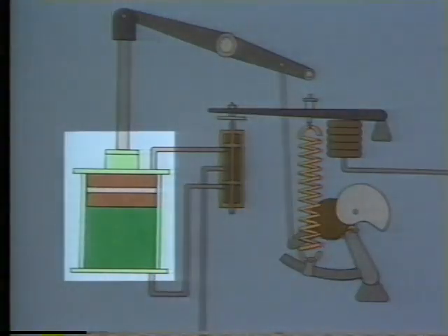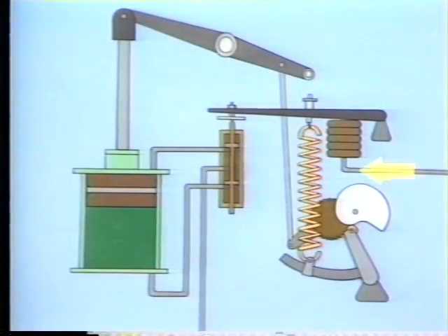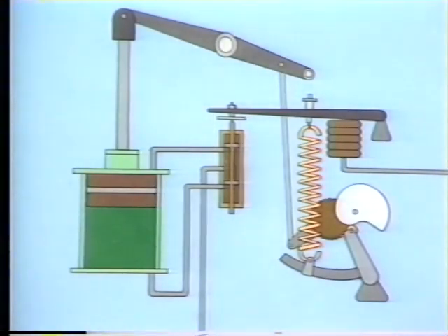Now the piston in a piston actuator should move a specific amount for the amount of force exerted by control air on the bellows. If the control air pressure is greater, the piston will move more. If the control air is less, the piston will move less. But as long as the pilot valve directs air to the actuator and allows air to bleed off, the piston will continue to move. This is where the feedback balancing mechanisms come into play.